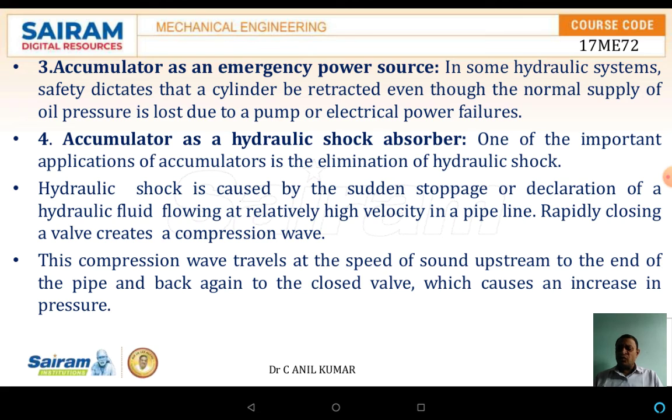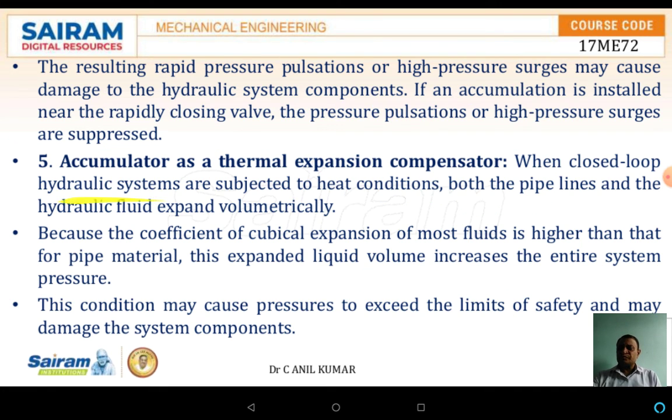Rapid closing of valves creates compression waves. These waves may fail the system, cause problems, or burst the hose pipes. To avoid these problems, accumulators are used as hydraulic shock absorbers.